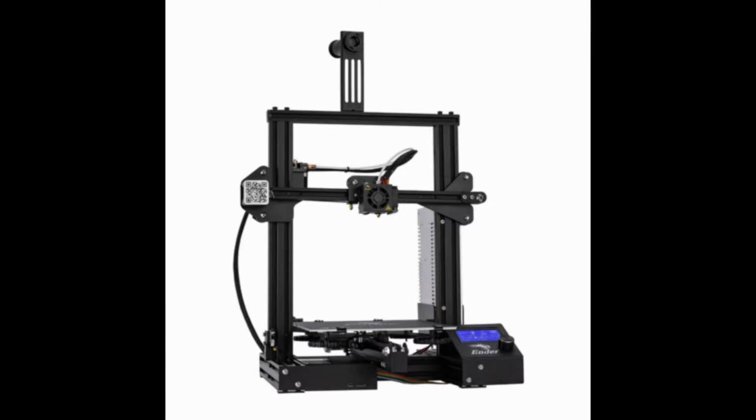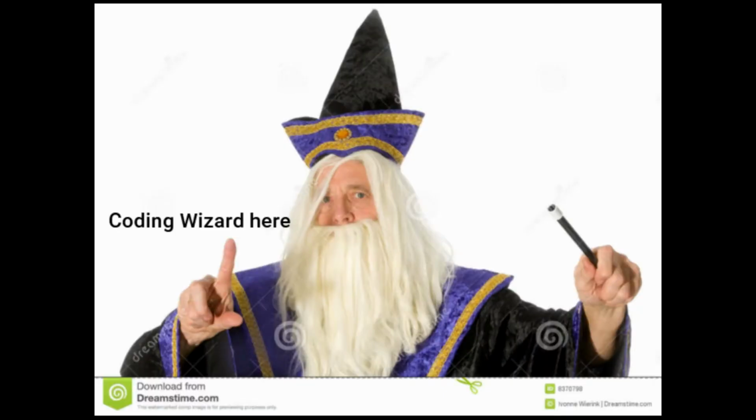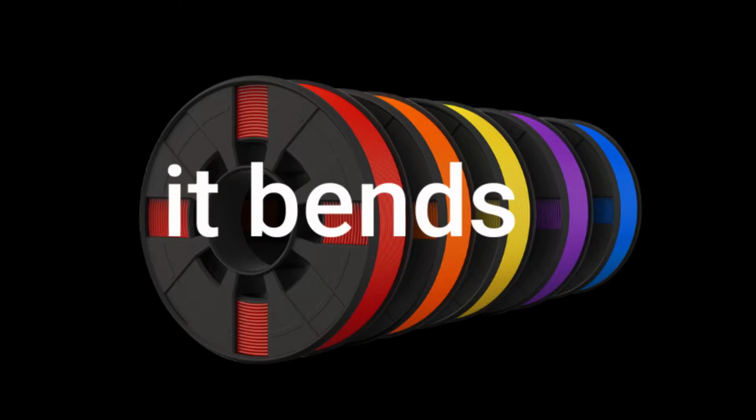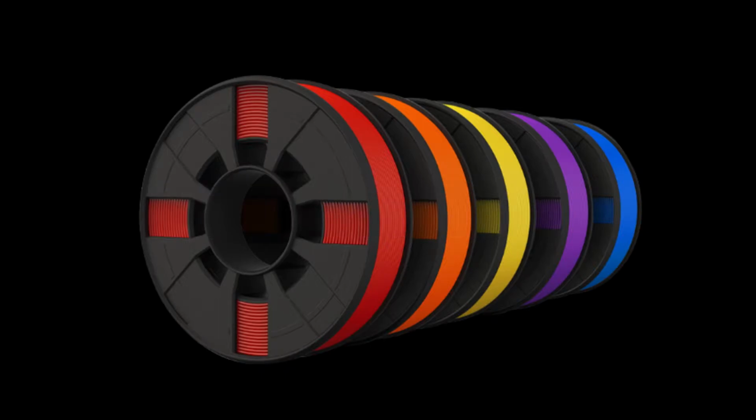My 3D printer, the Ender 3, is a very popular 3D printer. This is because it is a cheap and open source 3D printer, which is easy to upgrade and customize. Some very common materials used with the Ender 3 are PLA, PETG, and TPU. PLA, also known as polylactic acid, is a plant-based product used as a very brittle but easy to print material. PETG is a little bit more difficult to print, but is much more withstanding to high temperatures. And TPU, which is thermoplastic polyurethane, is a very flexible material.